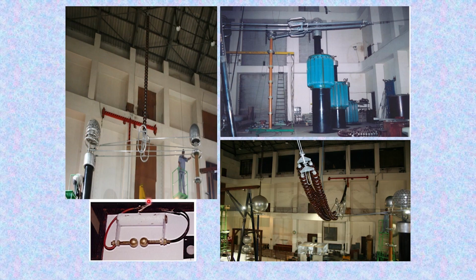So, the breakdown voltage across each spark gap is made for the entire string, and the values are noted, and finally the distribution is found out. This helps in proper design, whether the corona control rings which have been designed are properly grading the entire string, or whether the arcing horns or other arrangements used as grading rings are properly designed.